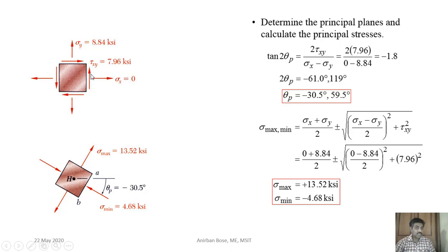This is positive because this is the positive x-axis, and that is why the shear stress direction should be in the positive y direction. Okay, so this is positive. Or in other words, you can think in that way also: if you consider any inner point within that element and this particular force is trying to rotate in the anti-clockwise direction with respect to some inner point, then it is positive.